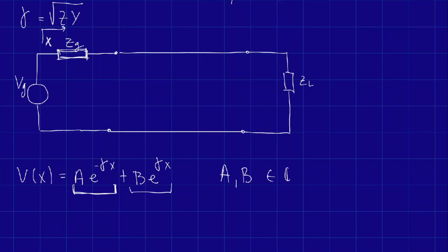But then you might say, why does the reflected wave right here have a plus sign? Well, the reflected wave first goes from the right towards the left, in this direction right here. And since we are not working with perfect conditions, the more the wave goes towards the back, the smaller it becomes because it loses some of it because of resistances. Let's say that this is x equals 1 meter, and this is x equals 9 meters. Since it goes in this direction, the more time passes, the more it goes towards the left, the smaller it becomes. So this plus sign also makes sense.